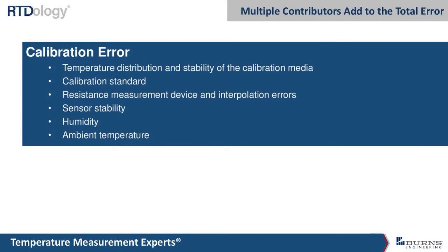Even some of the higher end calibration equipment is going to be affected by humidity and temperature. I know our lab actually has some parameters that we have to meet as far as temperature and humidity so that the equipment stays within its original uncertainty estimation.